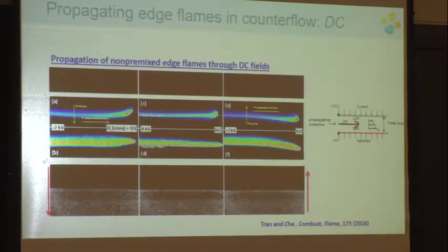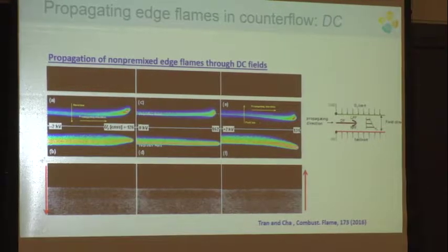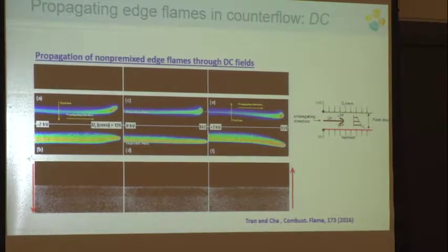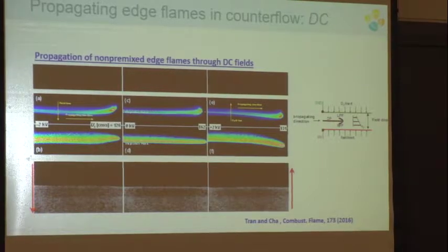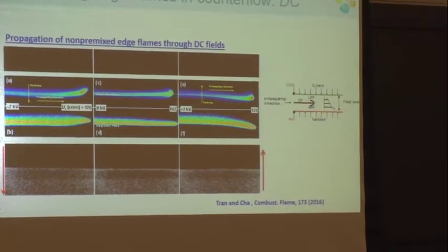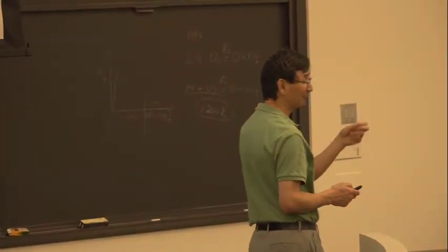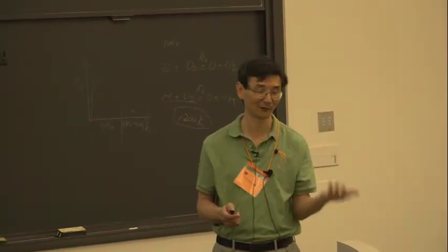And if it is yes, how? One way is that I create ionic wind, but ionic wind cannot really generate much. It only generates dynamics. The other way is that in the electric field, I generate electrons. The electrons might be able to collide with the fuel and break down the fuel and enhance flame speed. Third is that the electrons collide with the molecules and exchange energy, which may generate heating and enhance the flame speed.